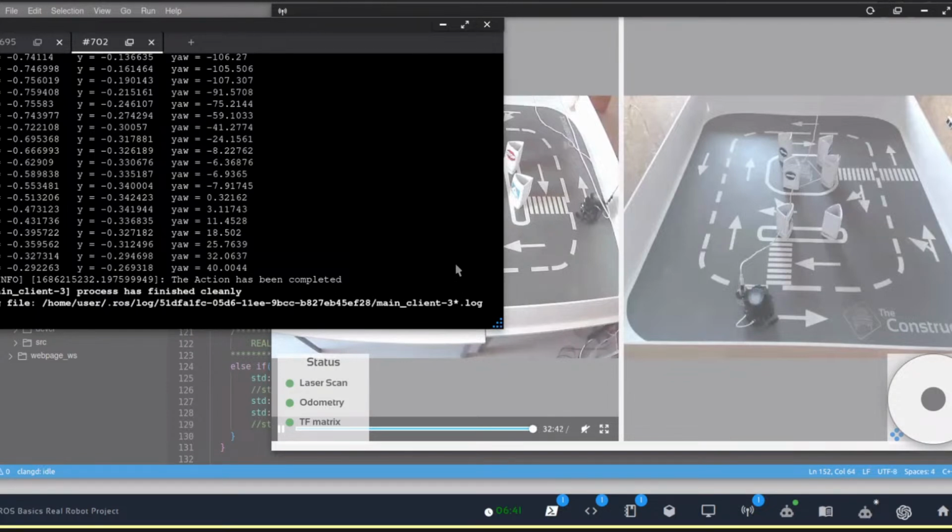So how do we know when the robot completed one lap? I did it experimentally by measuring the current distance the robot has moved. Let's say I put the robot to do some laps around the arena, and estimated a threshold, more or less the distance that the robot needs to travel in order to complete the lap.